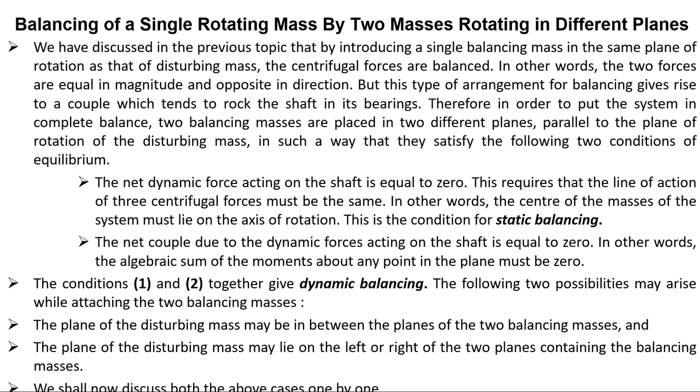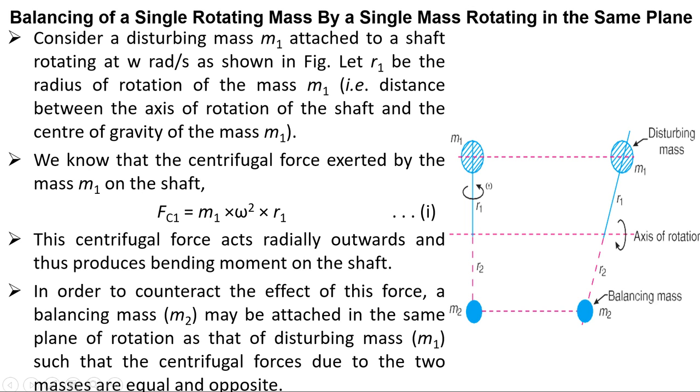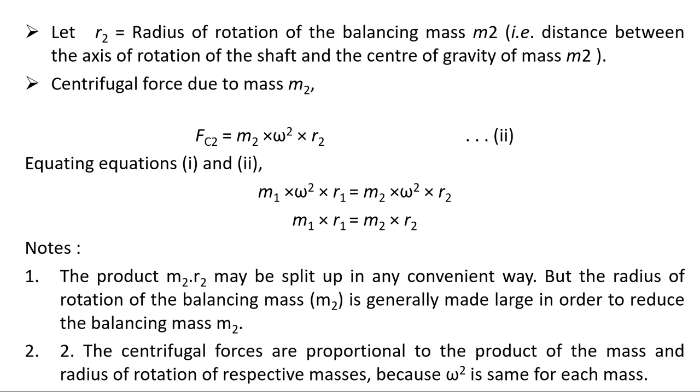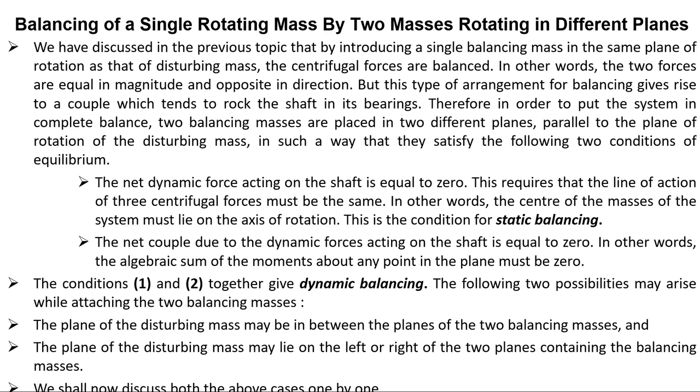Last class we saw the balancing where we used only the same plane, so there was no need to consider the couple. Here, as the plane is being shifted to another plane, we need to consider the couple also. The couple tends to rock the shaft in the bearings, and therefore, to balance it completely,